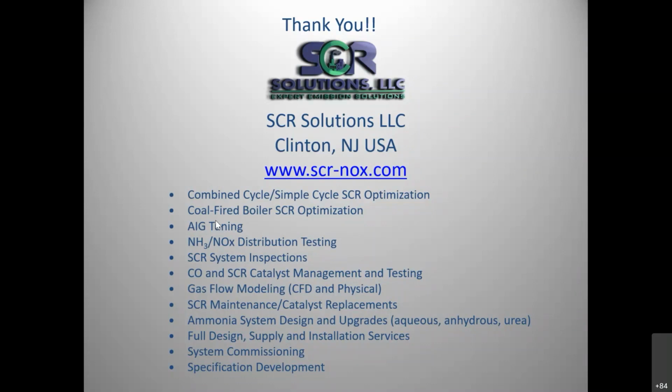So the AIG was designed to basically be self-supporting. We did install a center support column or tower, if you will, to support the ends of the AIG lances because they were coming in from both sides, and to allow for thermal expansion both horizontally and a little bit vertically. So it didn't need all that structure to begin with.